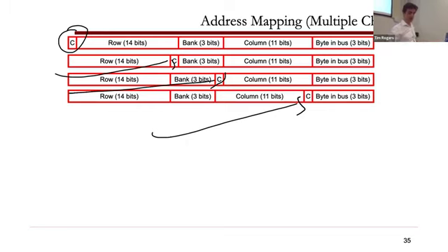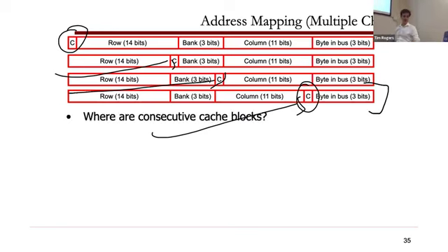So at this kind of funky configuration right here, what this says is my cache line is actually sprayed across multiple channels, right? So I've got 8 bytes of my cache line on one channel and another 8 bytes on another channel, which if all you're accessing is one cache line at a time ever, this is kind of what you want, right? Because you actually want to go to the 2 channels and light them both up to try to get the data. So the bandwidth for each block is going to be twice because you're going to get all those pins. But usually no modern memory system just has one access in flight. So this is not usually profitable. So it usually ends up tending towards the higher bits for the memory channel.